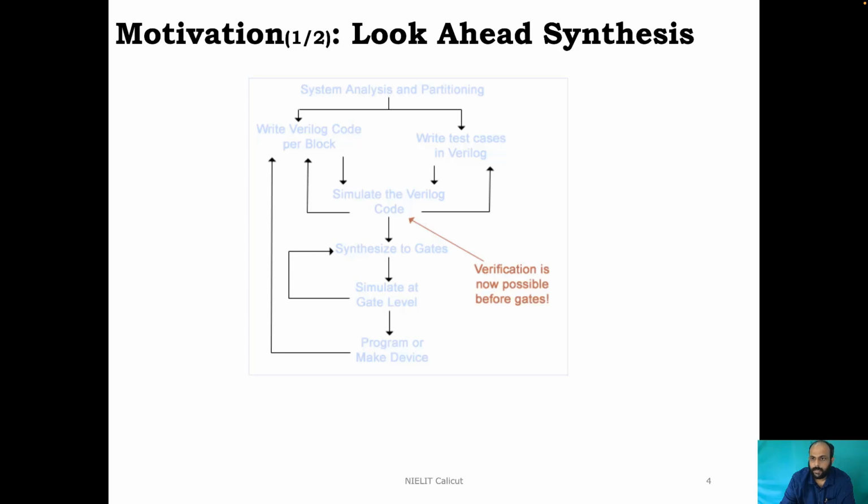We can call it look-ahead synthesis, because if the design is entered using a hardware description language, one obvious advantage is that it can be used to thoroughly debug the design before we go to the more time consuming processes involved in synthesis. I already explained that synthesis here means converting. So we can write the description as Verilog code.